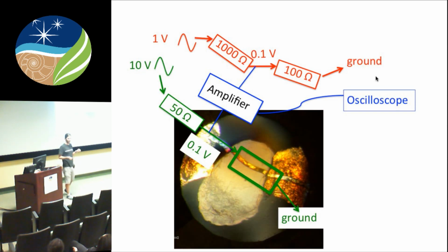Does anyone want clarification? Yes, Zhushua. Why is the resistance change in temperature? Because most pure metals have a few parts per thousand change in resistance per degree change in temperature. As you heat up a metal, there are more and more vibrations, and electrons collide with those vibrations. There are some horrible alloys that don't do this, but I chose to not use those alloys in my experiment.